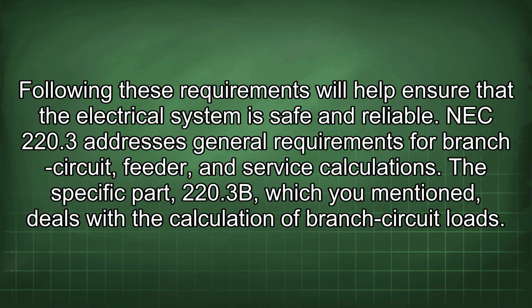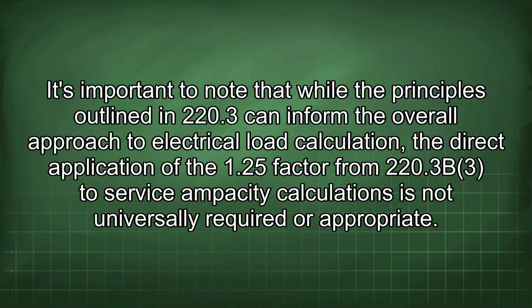NEC 220.3 addresses general requirements for branch circuit, feeder, and service calculations. The specific part, 220.3B, which you mentioned, deals with the calculation of branch circuit loads. It's important to note that while the principles outlined in 220.3 can inform the overall approach to electrical load calculation, the direct application of the 1.25 factor from 220.3B3 to service ampacity calculations is not universally required or appropriate.